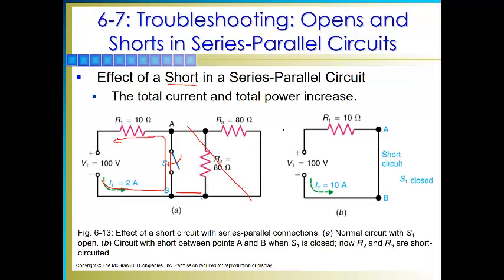Basically this whole section of the circuit gets eliminated because no current is going to go through there. Here we have resistance, and the current doesn't like the resistance, so the current will always go through the path where there is the least opposition to the current, and there is no resistance in this wire, ideally. So the current will just short this part out, and then the current will make this loop and the circuit gets reduced to this circuit right here.